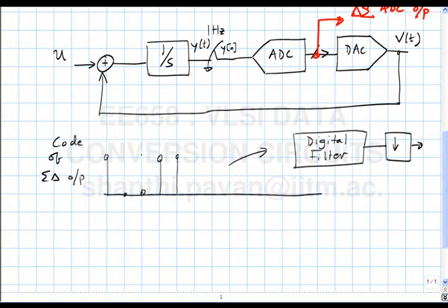Yeah, so please note that, in the simplest case, one simple way of realizing a digital filter is to use an FIR filter, which is basically the sum over k of C of k or W of k, the kth tap, times V of n minus k, with k equal to 0 to n.